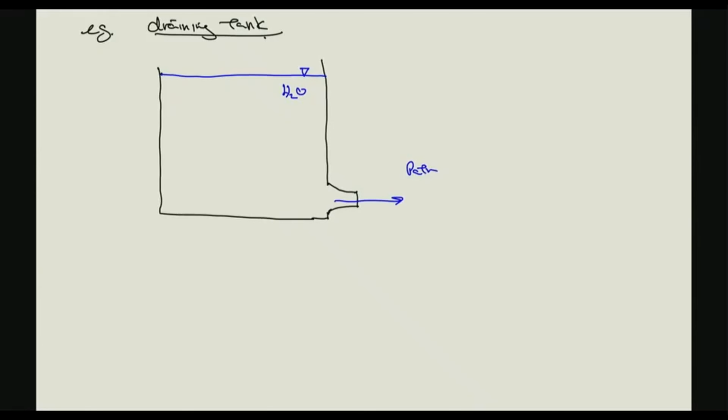So the atmospheric pressure, the surrounding pressure, is P atmosphere. And as you'll learn, when you have an incompressible flow and you have a nozzle, okay, so you have fluid that is internal, and then it exits out into the atmosphere, okay? If it's incompressible, then the pressure right here at the exit is equal to the atmospheric pressure, okay?